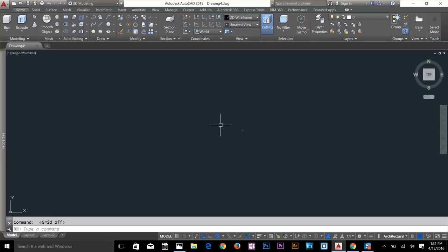So the area we have for our drawing would be an X value of 25 feet and Y value of 60 feet. Well, I'm not sure about the area, so I'm going to start by drawing a line. So I start from this arbitrary point and I give a value of 60 feet. That's roughly 60 feet, and I start another line from here to 25 feet, and then I right click. You can use enter, right click or spacebar, whatever you like.